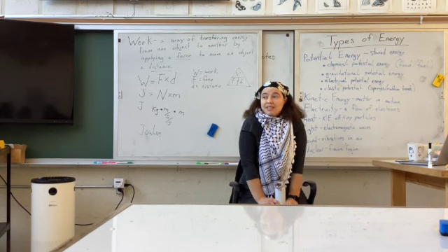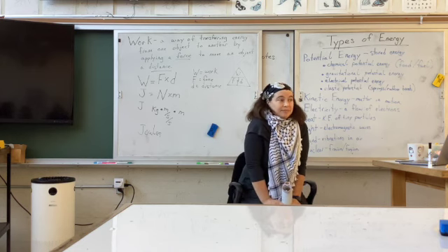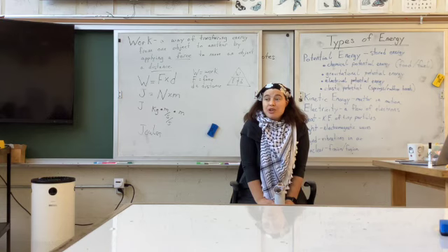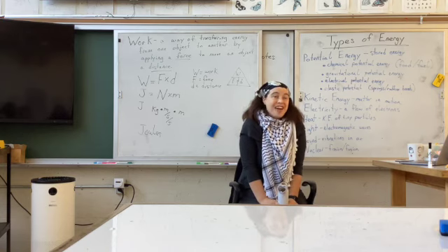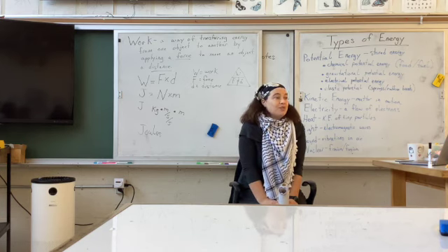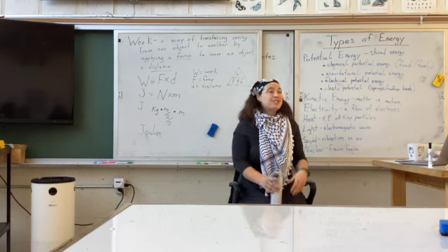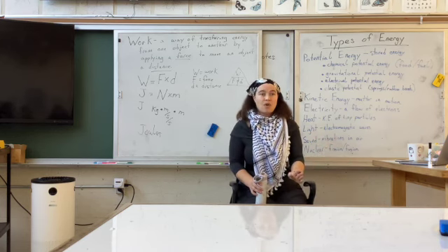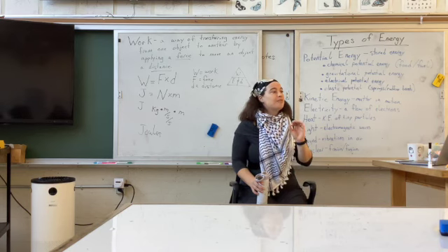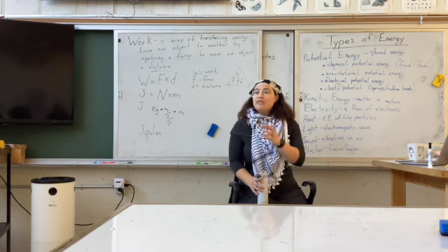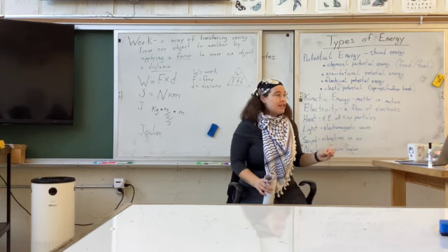The other big thing that's going to make a difference is stuff like air resistance. Air resistance is proportional to velocity. The faster this thing goes, the more air resistance it's going to be up against. So you actually don't want your car to go fast. You want your car to move slow and steady, because the faster it's going, the more air resistance there's going to be. So you can reduce how much energy is going into moving air out of the way instead of making your car go forward, by simply having it creep forward at a nice, slow, steady pace.